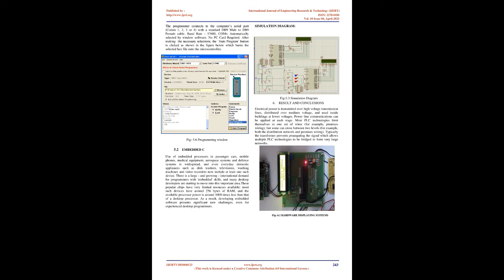the Rebuild All Target Files to compile the program as shown in the figure below. Fig 5.4 Save All and Build All Target Files buttons. Fig 5.4 shows the program has been successfully compiled. It can be simulated using the integrated debugger in Keil MicroVision. To start the debugger, select Debug > Start/Stop Debug Session from the pull-down menus.